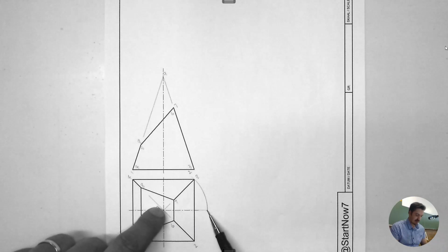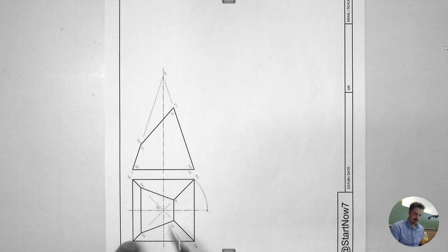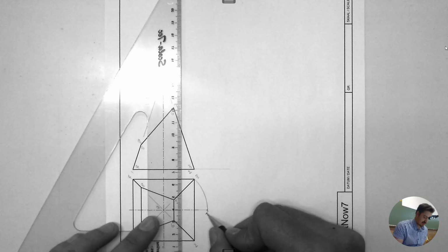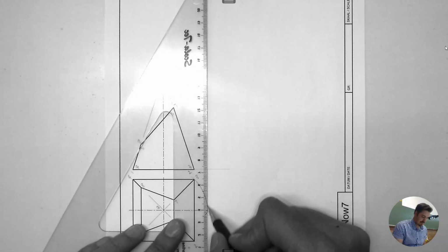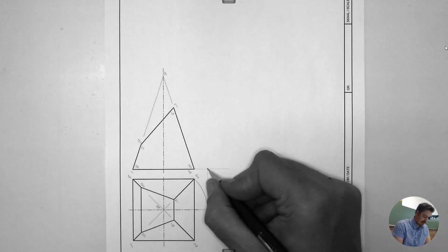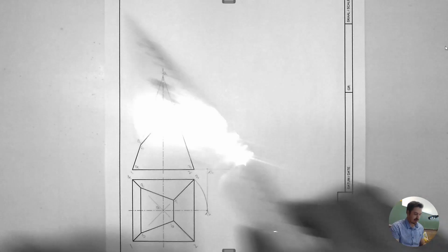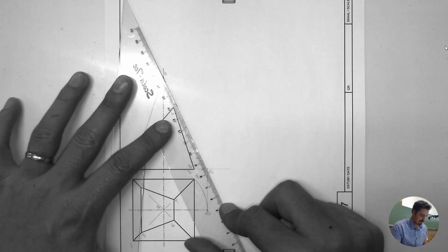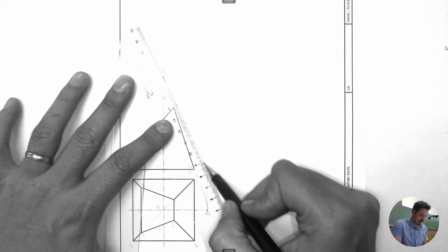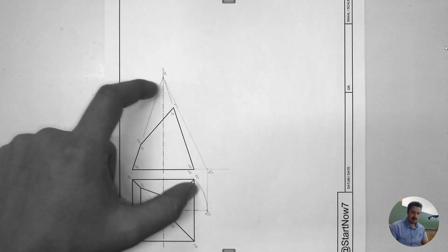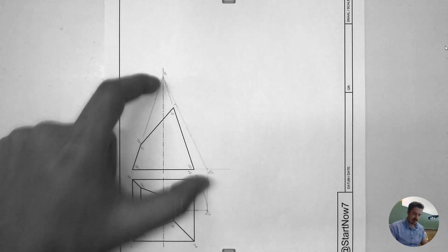It doesn't matter how you project it, right? So that is the length that all of these points are. So in order for you to start the drawing, you need to have that point there. So let's just project the base over or across. We project this true length up onto the base so it connects there. Once you have the true length there, you go ahead and you connect it to point A, because now it is a pure and accurate representation of the true length, what that line really is going to be if you place it here.